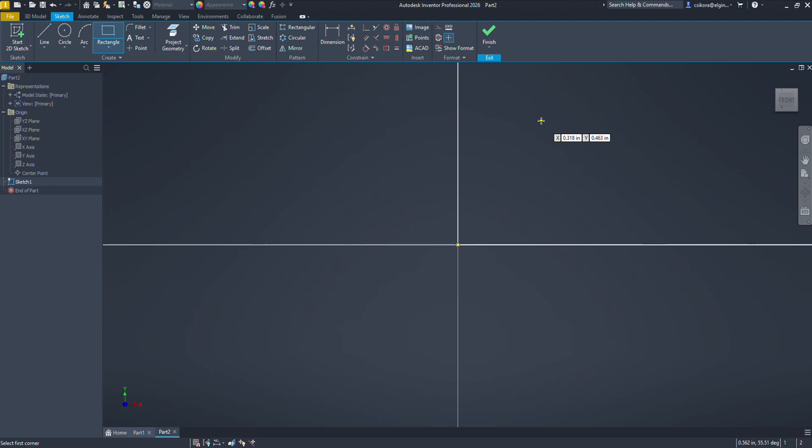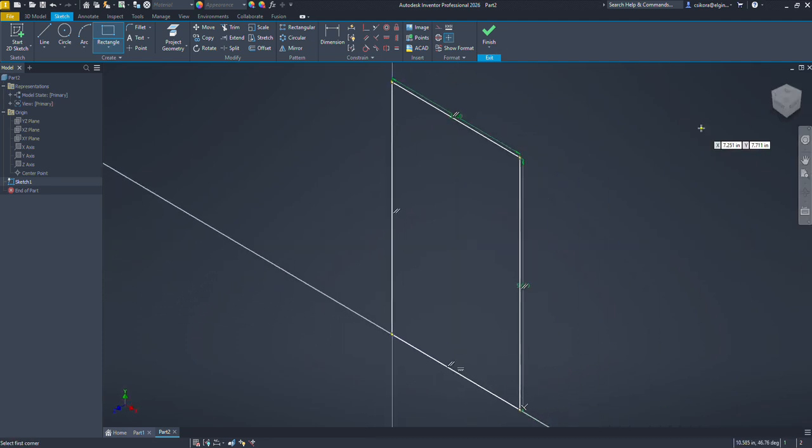You'll probably find the home button. You could click on that, or you could go to the home button right up here on the viewport. This is our rotation box. Don't click on that just yet, but click on the home button, and immediately you'll see this home button actually throws us into an isometric view, whereas the other one just keeps us in the front view orientation. So perhaps in this case, because we're working on 3D modeling, let's click on that home button so you get the same view.